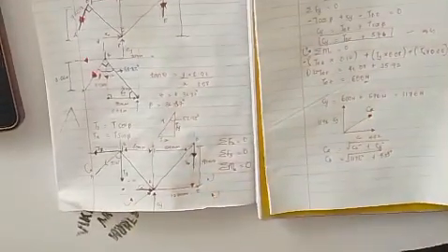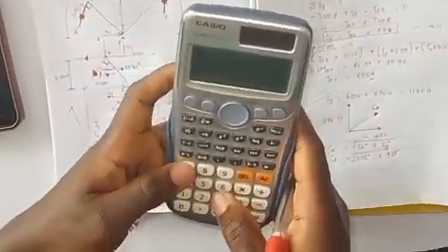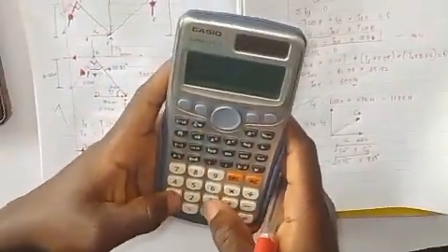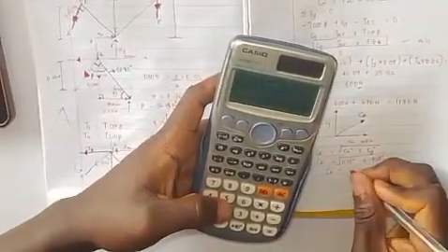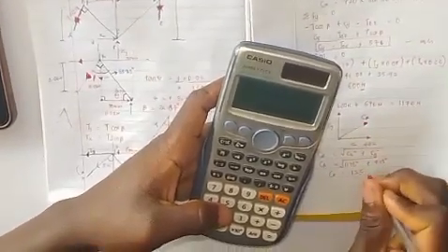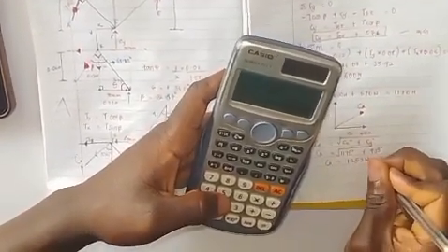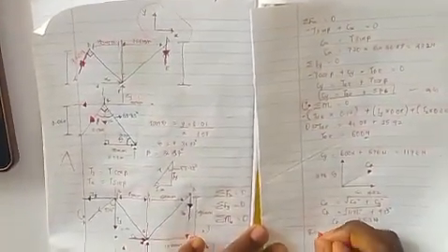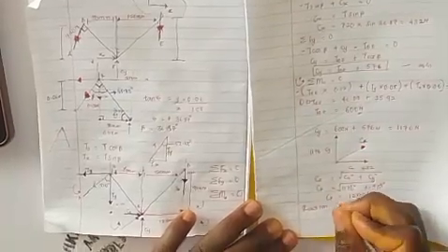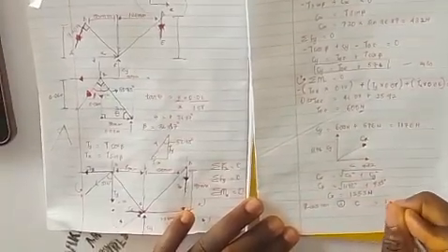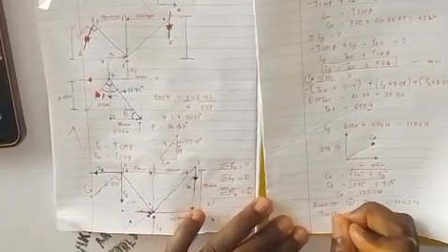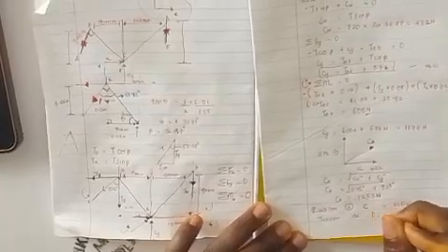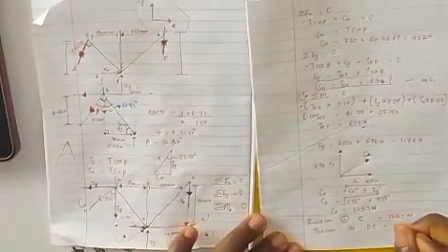So now let's calculate this. So that means we are having the square root of 1176 squared plus 432 squared. So that means we are having our Cr to be equals to 1253 Newton by approximation. So that means the reaction at C is equals to 1253 Newton. Then tension at DE is what? Your 600 Newton.